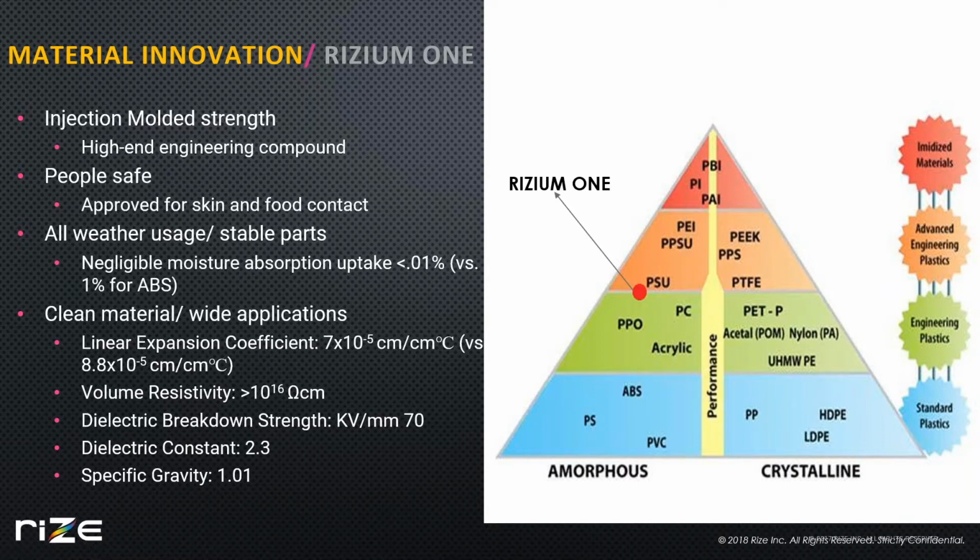You get the material, put it inside the box, put it outside for a few months. When you go to print, you get very high quality parts. And once the part is printed, basically it doesn't change shape or wick moisture over time. It has very low coefficient, very good volume resistivity. And also this particular material is used a lot in the semiconductor industry for packaging, for part designs today.